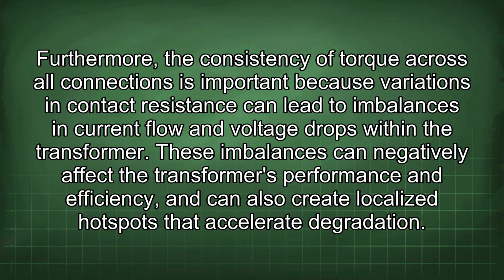Furthermore, the consistency of torque across all connections is important because variations in contact resistance can lead to imbalances in current flow and voltage drops within the transformer. These imbalances can negatively affect the transformer's performance and efficiency, and can also create localized hotspots that accelerate degradation.